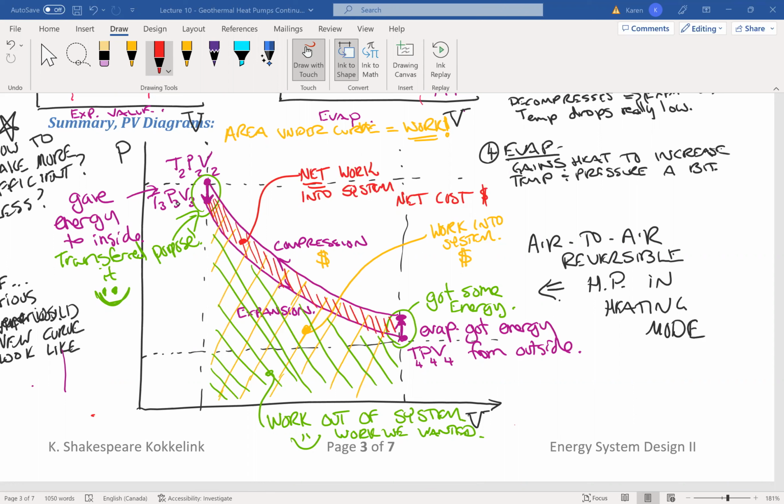What if the compressor were more efficient? What if now the compressor is the same? What if the evaporator is less efficient? What, because you haven't cleaned out the grate and it's full of leaves? Now put that back the same.